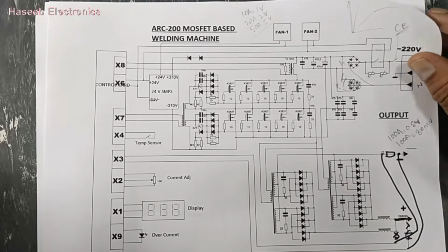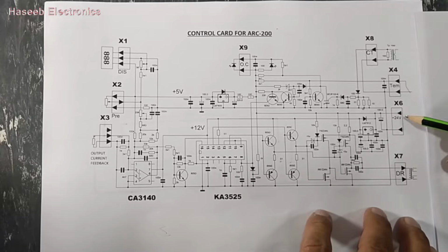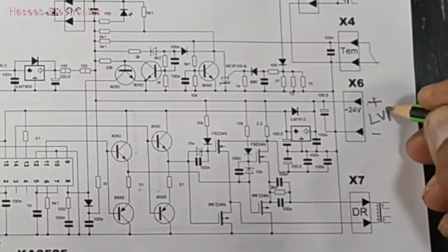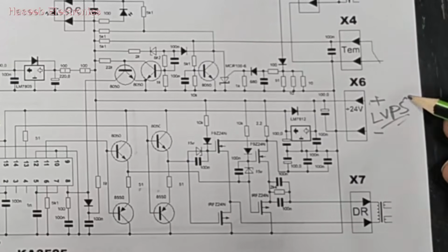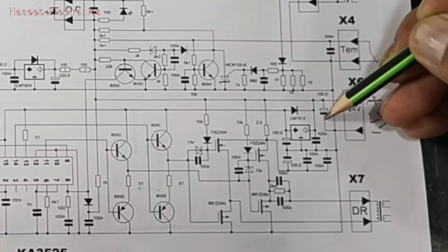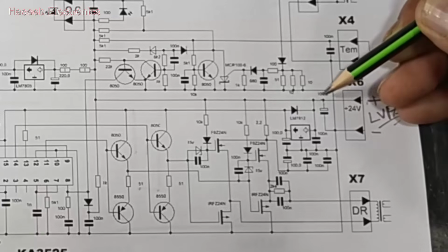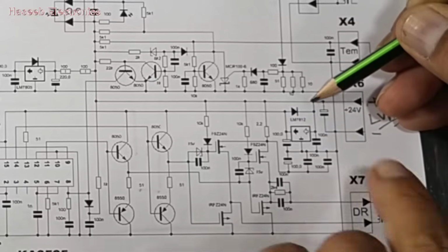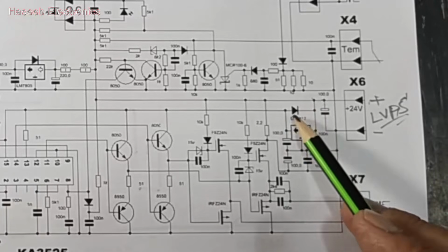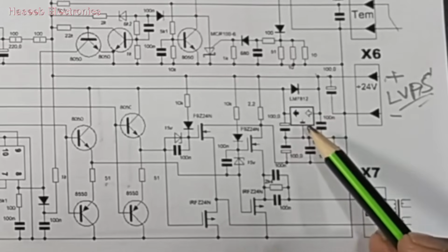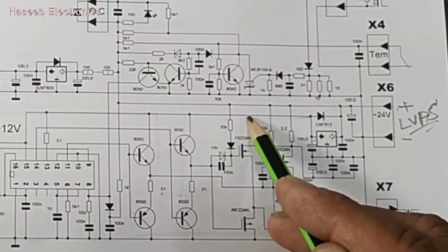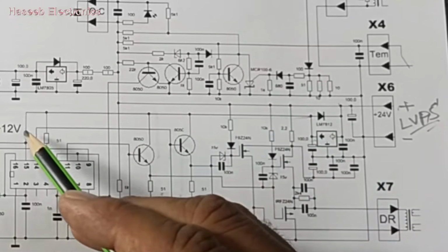Let's check the control card. In the control card, as we discussed, we apply 24 volt here, positive and negative. This is from the LVPS, low voltage power supply. That is 24 volts. So 24 volt is applied to this capacitor. This capacitor is a charged 100 microfarad capacitor. Then this positive voltage reaches here, and it will enter this LM7812 regulator. The output of this regulator is here, and we will take this regulated 12 volt here at pin